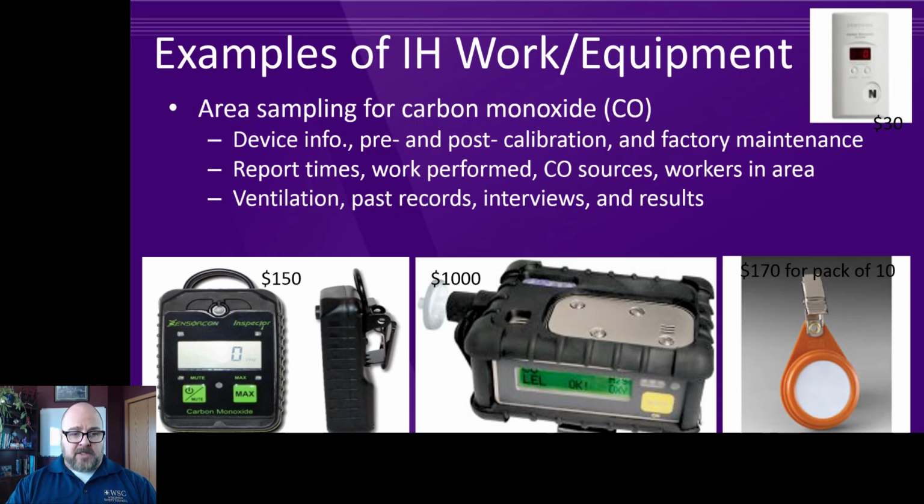We do process it and expel it, but they tend to treat you in an oxygen-rich environment to try to return you back to status quo quicker. It basically comes from burning carbon. So like a powered industrial truck, a fork truck running on liquid petroleum or LP, the exhaust pipe may be giving off 10,000 parts per million. So if you're in an enclosed area and that thing is running dirty, that room or space could fill with carbon monoxide very quickly.